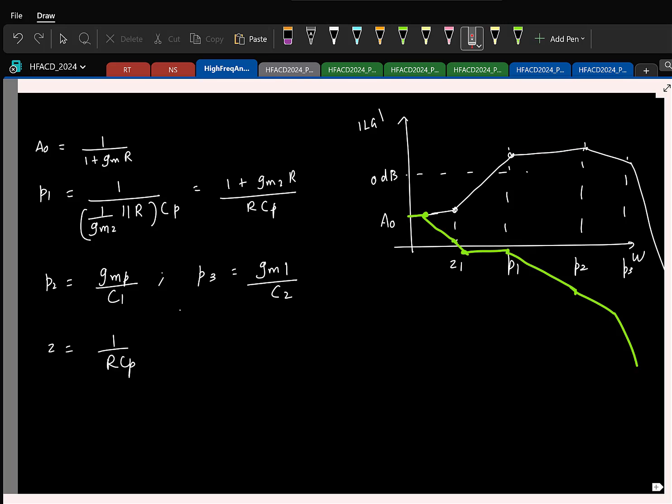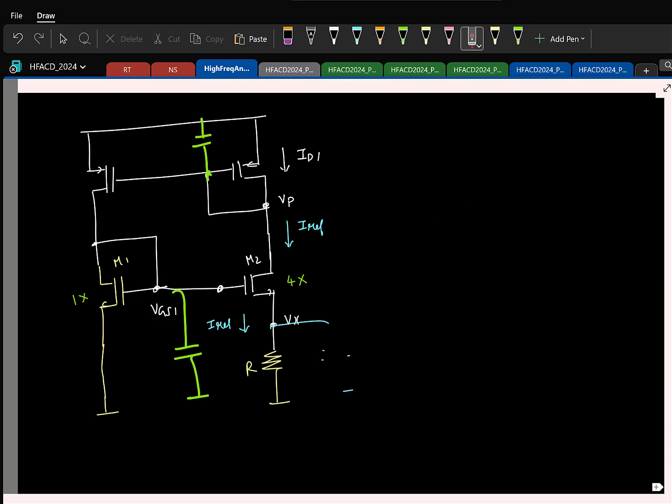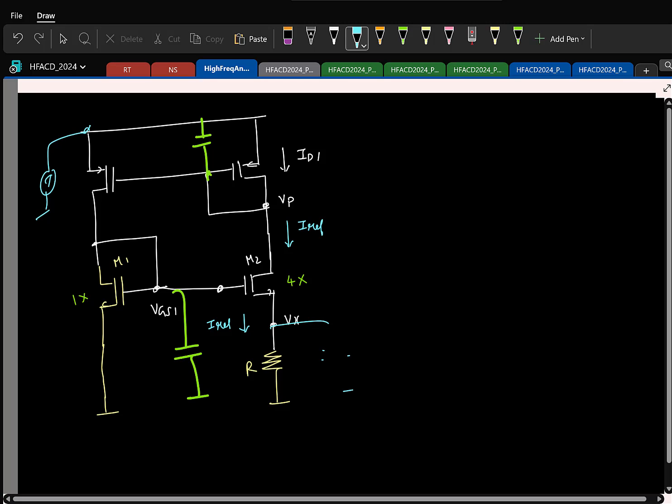Okay. So what disturbance do we want so that the positive feedback becomes effective? I mean, there can be any noise in the circuit, right? There is always noise in the circuit. So essentially, if there is any kind of current injected in the supply or somewhere, that's going to kind of blow up. The other thing is, you can also have a case. Typically you will not connect the supply all the time, right? The circuit is going to be off and you power it on. So which means VDD is not a constant, it is a step. That is enough excitation for this positive feedback loop to kick in.